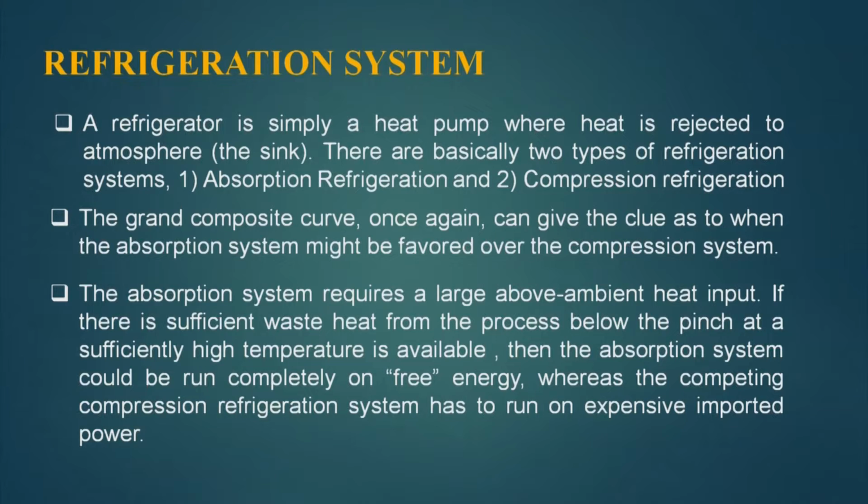If the situation is so, we will certainly select the absorption refrigeration system, and if it is not so, then we have to go for the compression refrigeration system, which needs power as an input, and hence it is costly.